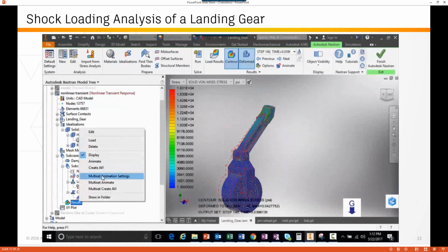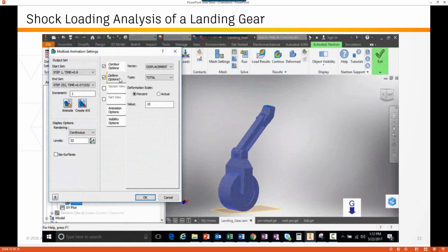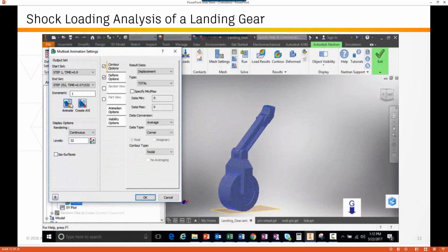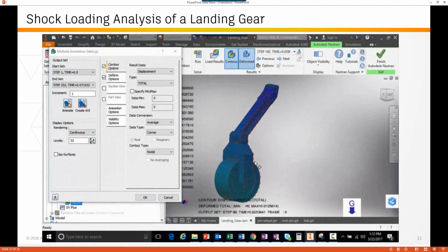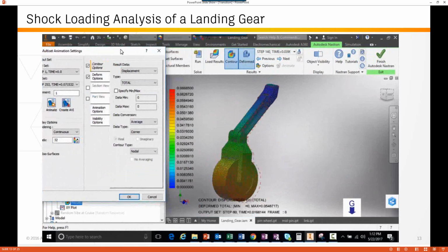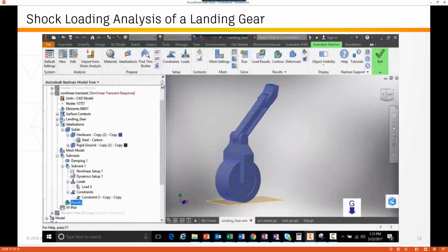I think one of the most critical aspects of FEA is the ability to animate our analysis. This is critical so that we can analyze how the structure likes to move over time. In a situation like this one, where we're analyzing throughout time, I can plot that time behavior and truly understand how my structure likes to resonate. I've got a major spike on the first load, and then eventually my system is going to start to dampen.